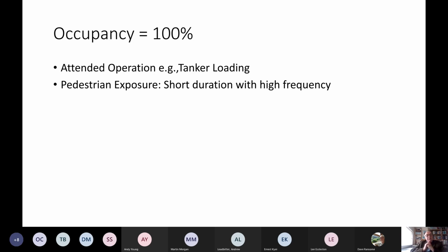And they would only transit the hazard zone for 10 seconds was the estimate. But that 10-second exposure, well, potential exposure, would arise quite frequently. Let's say every half hour somebody would walk through the area and be exposed for that 10 seconds. Now, if you take the 10 seconds as a proportion of the time, just doing the simple percentage calculation, you end up with a very small number, and then you could plug that in as a conditional modifier, but that would be a complete fraud.